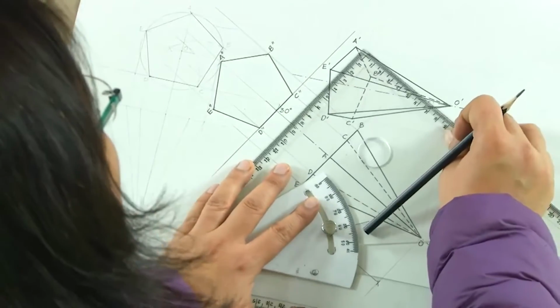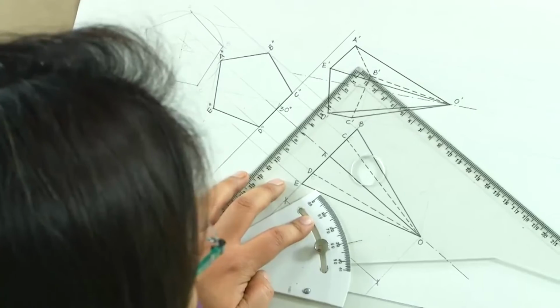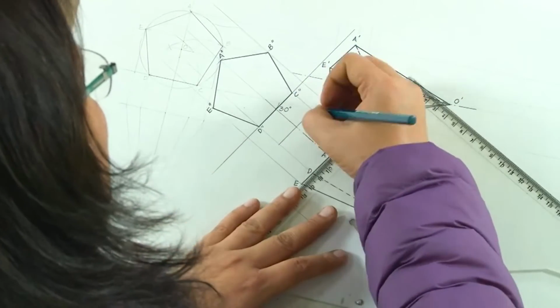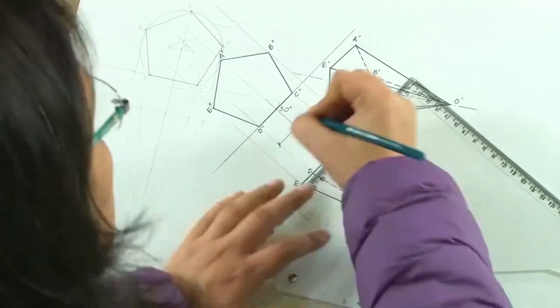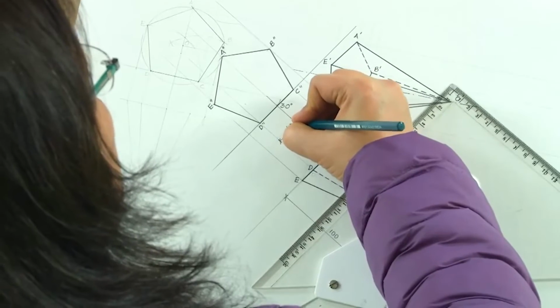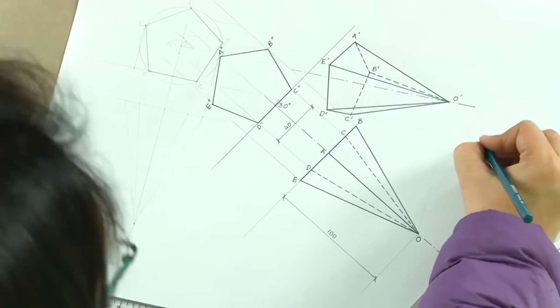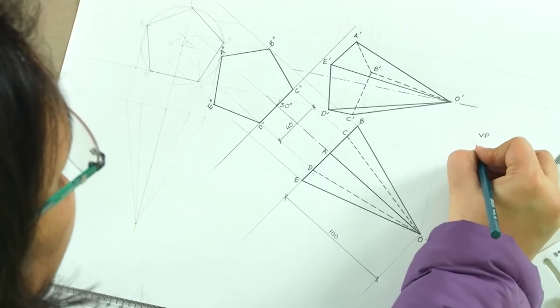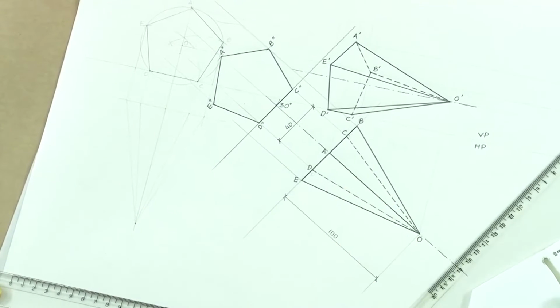and what we get is the true size of the side here. So, we can also draw it, mentioning the dimension of this, which, to begin with, we had taken as 4 centimeter. So, this is 40. With this, the projection of a solid, a pentagonal pyramid inclined to VP but parallel to HP is drawn, and this is where we will see the true shape of the base, the front elevation and the top view, the plan of this pyramid.